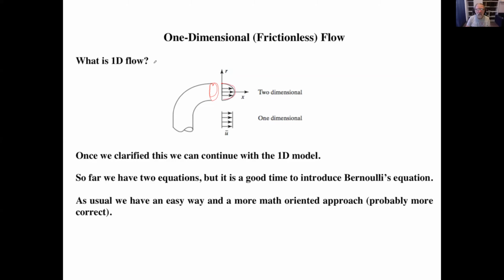So if I claim one-dimensional, then I would like to represent that flow rate with one number, velocity, and therefore I assume that the velocity profile is constant, and the magnitude of this arrow here is equal to the average velocity here. So these two are identical for practical reasons, okay? So once I made that, I can continue with that. And now what I'm saying here is that I introduced to you the one-dimensional conservation of mass and momentum.